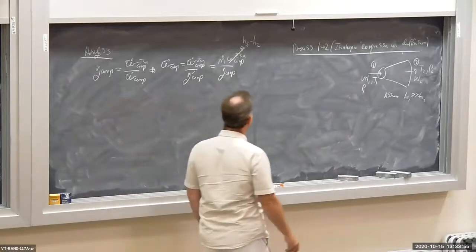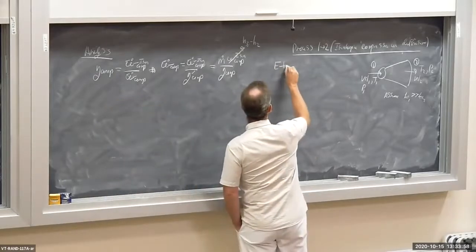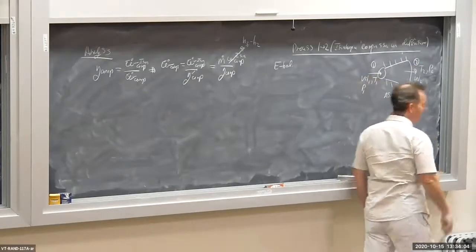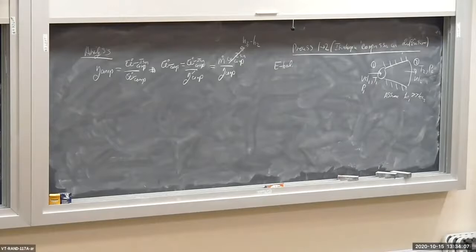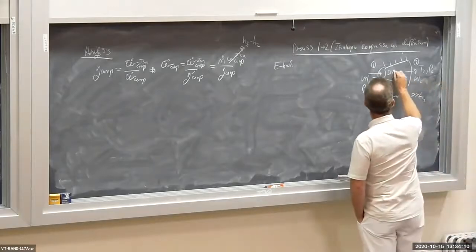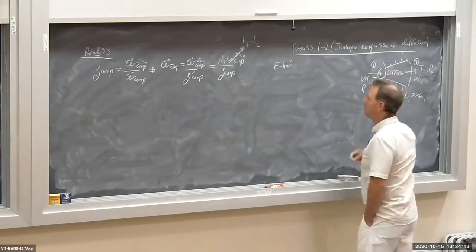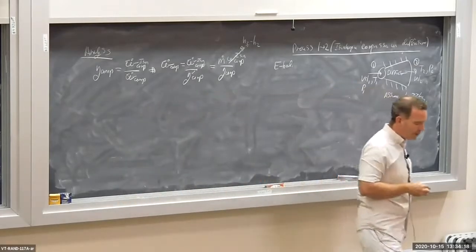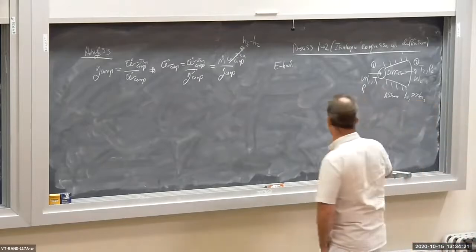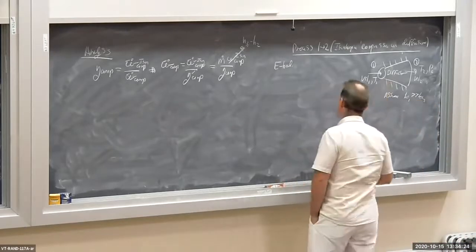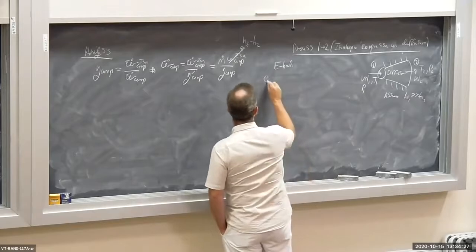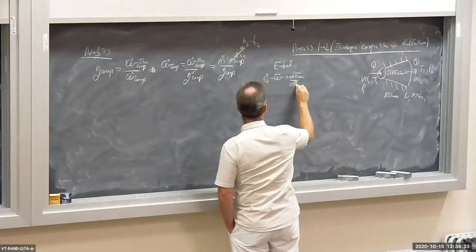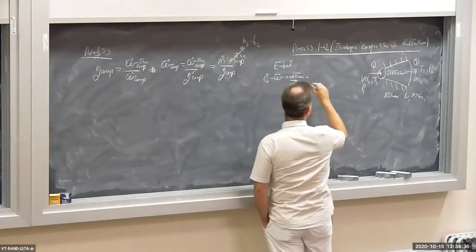Let's apply the energy balance. It is an insulated device, this diffuser. So there's no heat transfer, there's no shaft power, there are no shafts in there. I'm going to neglect changes in height or elevation. So Q dot minus W dot is equal to dE CV dt. I'm only going to write this once. We won't do it for the nozzle. The nozzle has a similar analysis.